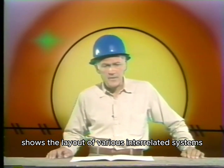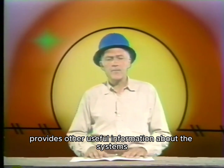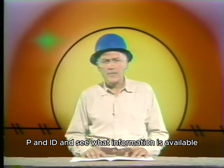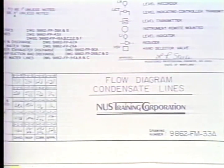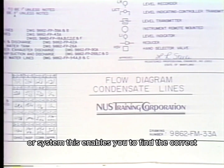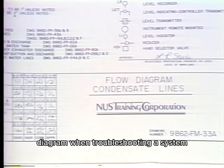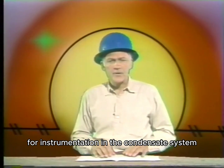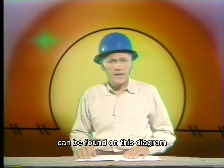A P&ID shows the layout of various interrelated systems, but it also provides other useful information about the systems. Let's take a closer look at a P&ID and see what information is available. Titles of diagrams describe the overall function of a particular loop or system. This enables you to find the correct diagram when troubleshooting a system. The title of this plant's diagram tells us that we're looking at a flow diagram of the condensate lines. So we know that information for instrumentation in the condensate system can be found on this diagram.